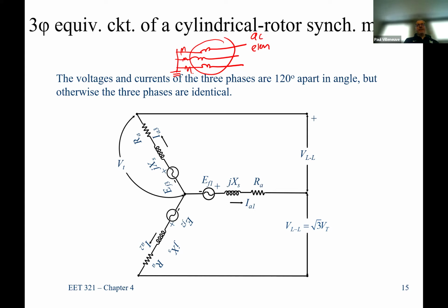So would that be a Y connected generator? Do you still call them Y or delta? Yep. Still a Y connected one. This one, it's not grounded necessarily, but it would be. Every generator is going to be connected in a Y or delta. Most generators, you would connect them in a Y, and you would ground the neutral, maybe not a solid ground as I've shown here, but you would ground it through something. And there are major reasons why. That's more of a protection discussion that we have, but you would certainly ground them.